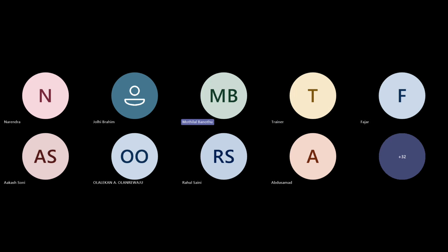Sir, my second question: this droplet size, how will you decide? Because this is continuously varying. The liquid and gas droplets, in microns. You are saying that to calculate the drag coefficient there is some dp, the particle diameter. How will we estimate this? Is any software required? No, no. You have to consider how much particle diameter you wish to separate. This is up to 150 micron, up to 1000 micron. Sorry sir, your voice is not clear, it is breaking.